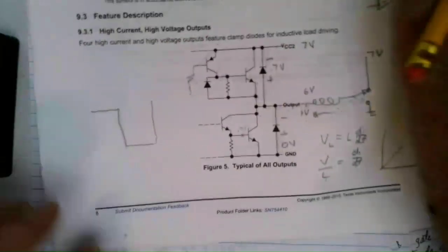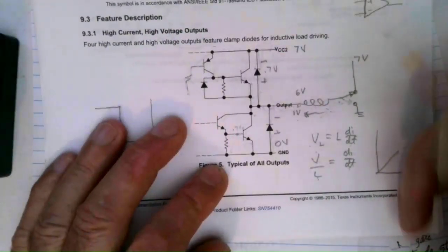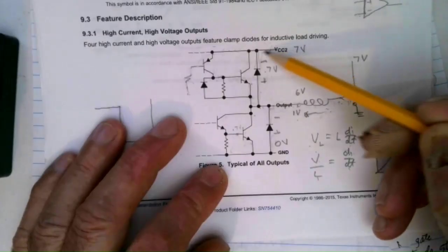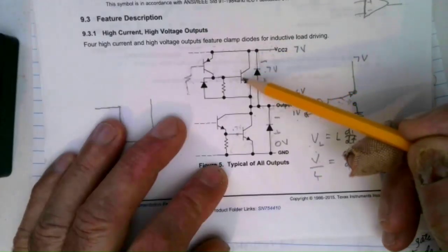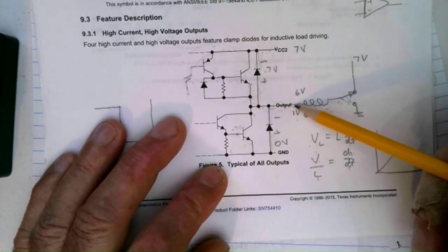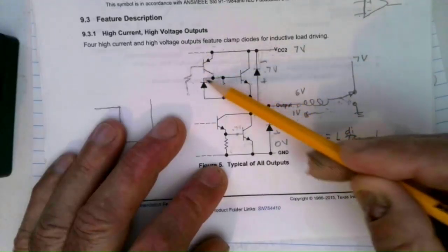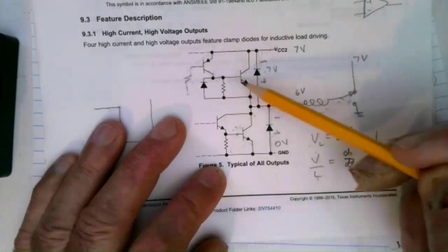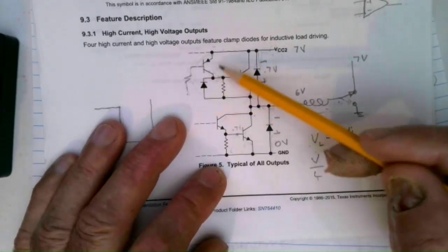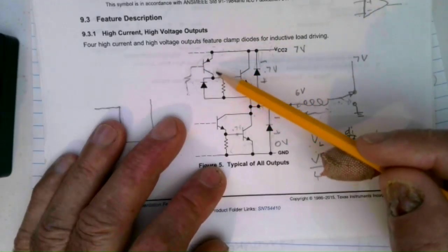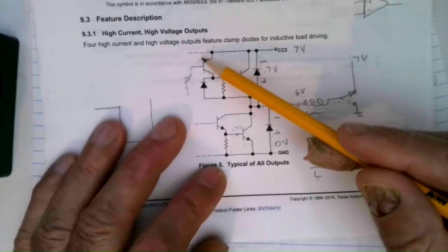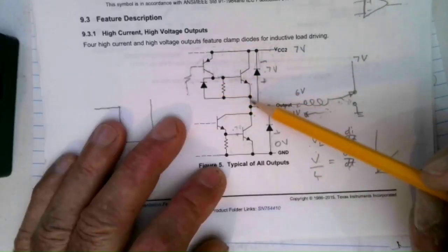And as you see, there's your supply, and you've got your emitter follower driving the load, and a PNP pulling it up. So, on integrated circuits, PNPs can be pretty weak. And that is the issue here. So this thing will handle an amp, I think.